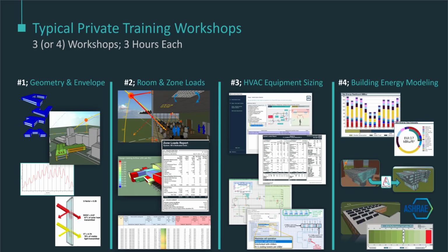And block number 4 is the whole building energy simulation, where we'll generate outputs like energy, site and source energy, energy cost, carbon emissions, water usage, thermal comfort of occupants, and code compliance. So if you're meeting the local codes, whether that be ASHRAE Standard 90.1, Title 24 in California, or NECB in Canada, we do energy code compliance all over the world. That last one can be quite regionally specific, I guess is the theme of what that is all about.